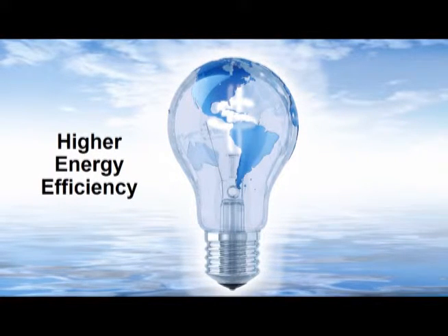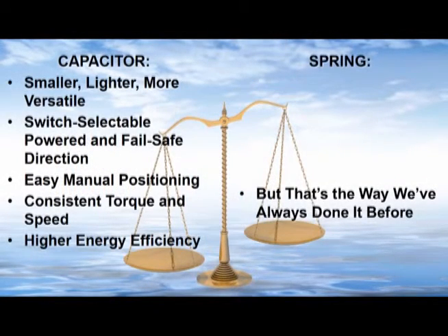Spring return actuators require extra motor torque to overcome spring resistance on every cycle, and they consume much more power just to maintain a stationary position. After all these substantial advantages of capacitor drive are understood, few people will still insist on specifying old-school spring returns just because that's the way it has always been done before. Capacitor drive is clearly the future of fail-safe.